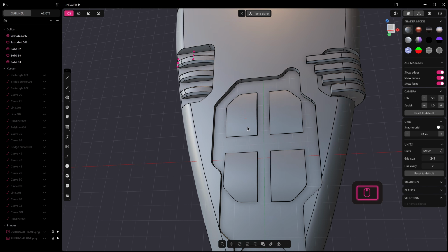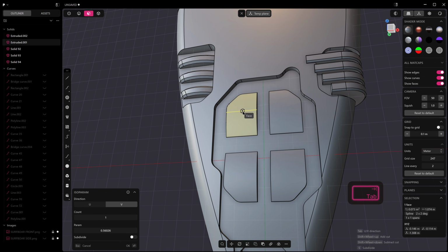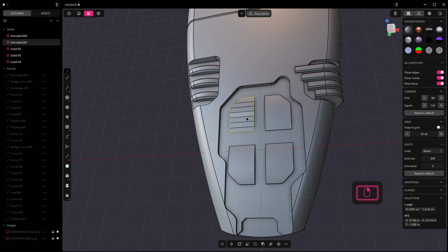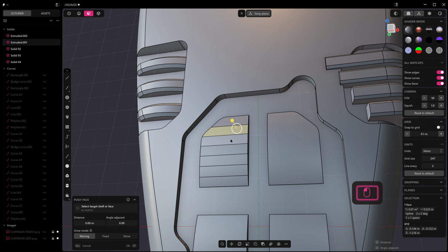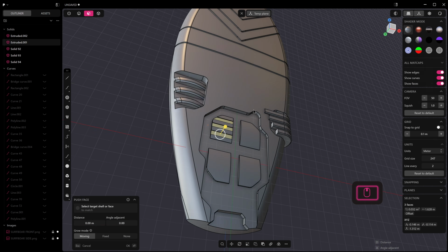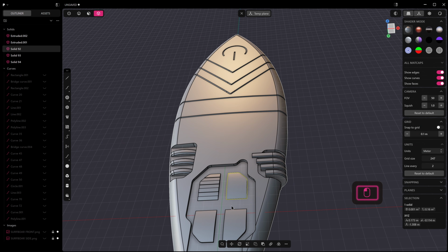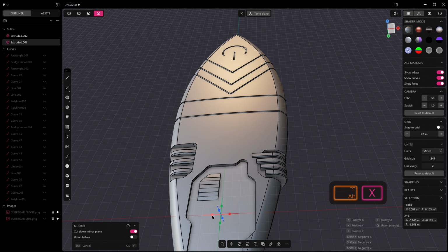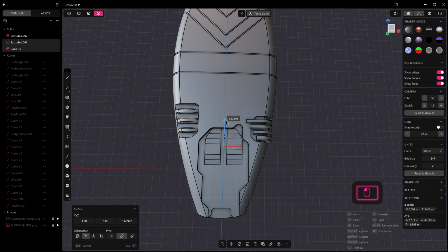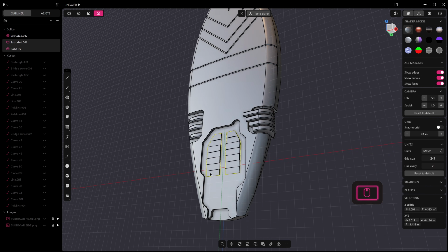Okay, and then with these, we could ISO param by pressing Control R and Tab, and hold down Shift to add more. So I guess these could be kind of like foot pads. We've got some utility here. Okay. And let's just delete these ones here. And let's mirror that again. Okay. And I might scale that on the X. And that looks pretty cool.